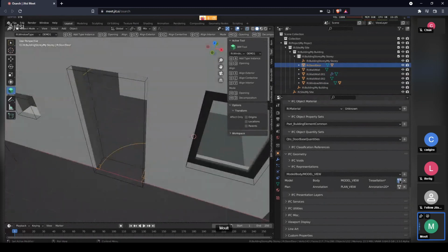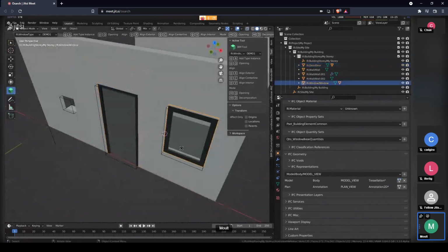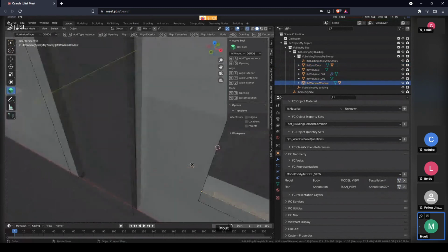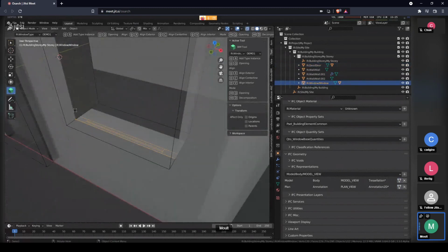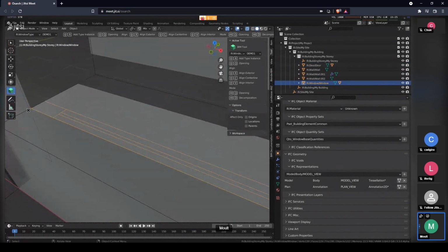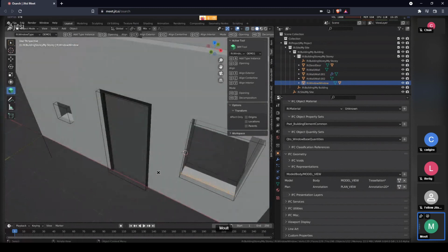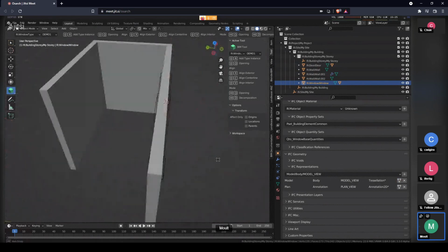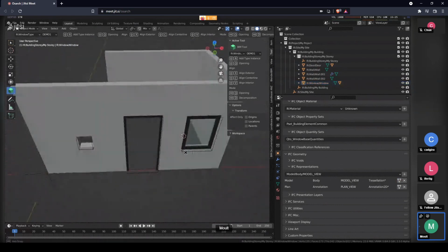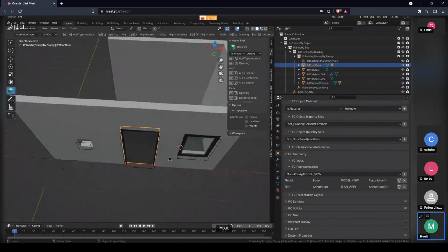And I'll switch back to the 3D view of the door. So same with the window. It has a little 2D symbol over there. And because it's 2D, it inserts at the object origin. So that origin circle is pretty important to pay attention to. Because it's 2D, right? It doesn't know where it needs to go.